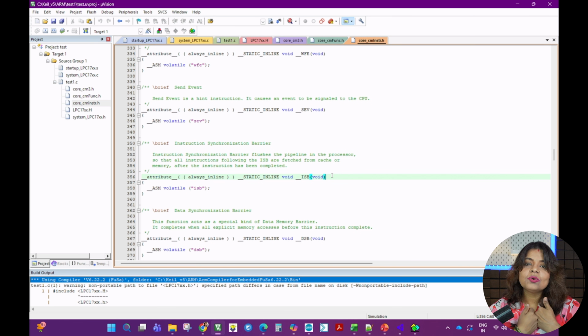Your code size is going to increase for sure when you're writing code in C. But when you're writing in assembly, you're writing only the defined assembly instructions, so the code size is also reduced overall. So if you want to develop the best optimized code, the code which occupies less space, and whose execution will also be faster, then I would prefer assembly.